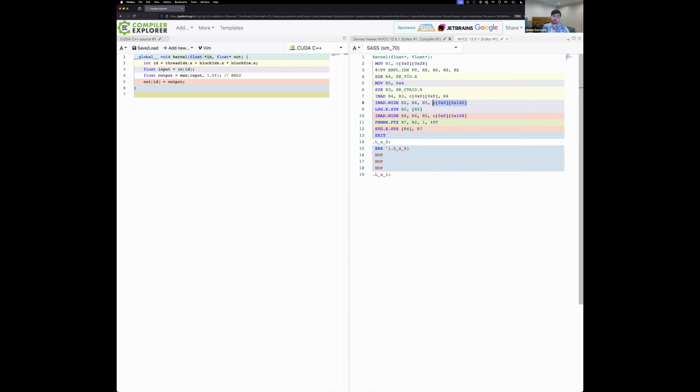It could miss all the way to even potentially system memory. Actually, no, I think it could miss in the memory units and end up taking more memory management units and take more than 1,000 cycles. So you've got a random instruction stalling everything for 1,000 cycles, which is extremely rare in practice, but it highlights the complexity of the architecture that something like that is even possible.